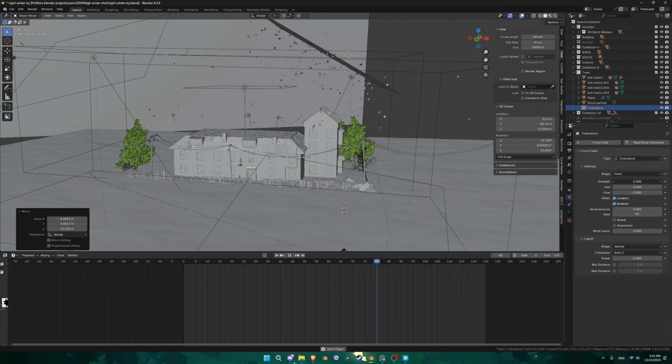I go inside one of the windows and give them a solidify modifier, remove the glossy and add a glass shader instead. And I bring in an image of a kitchen and blur the glass a little so the viewer can't really see what's going on inside.